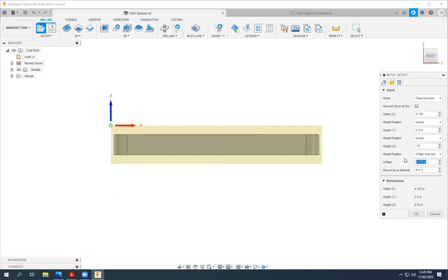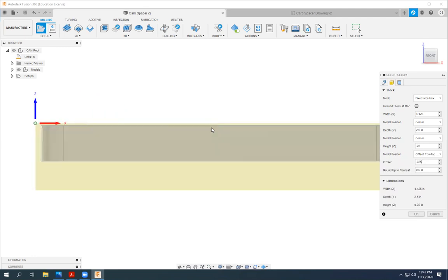But we'll use a face mill, which is a milling cutter used to mill entire wide surfaces. And we want to take off 25 thousandths worth of stock. So this way, we'll define the top of our part as being 25 thousandths above the actual part that we want to reveal. All right, so once we've defined that, we've got extra stock on each side that we can mill off, extra stock on the bottom for our work holding to be in the vise, and then click.